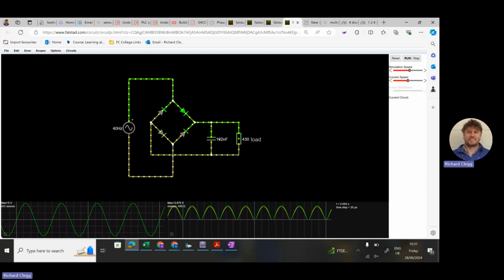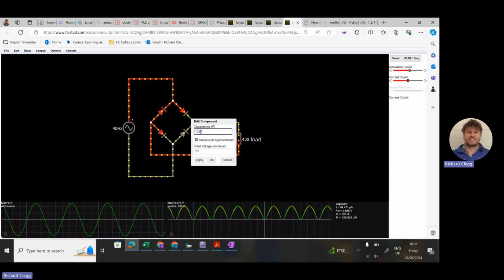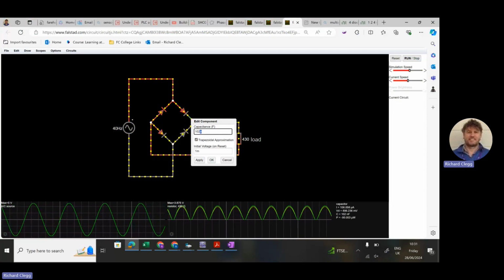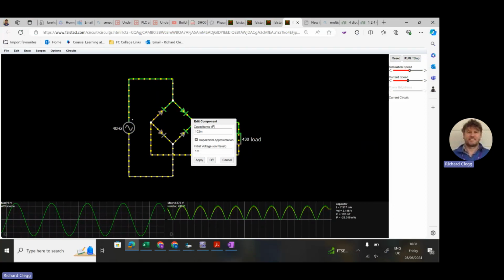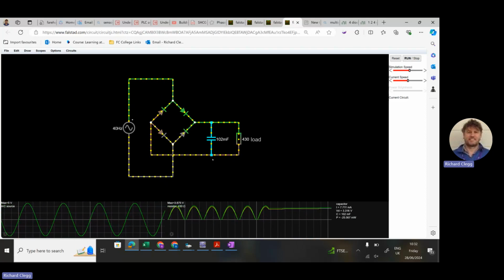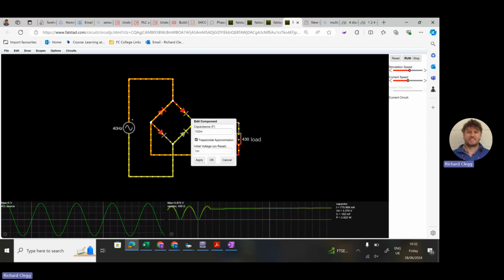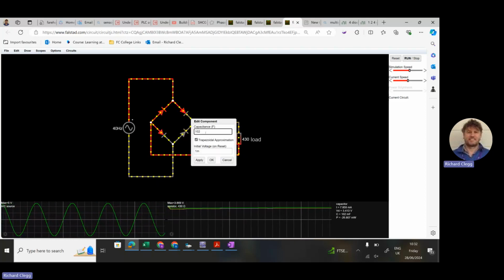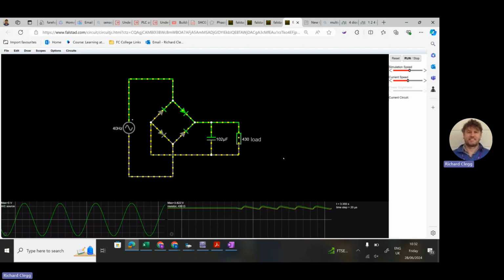So if you put a larger capacitor in there, it's going to smooth to a much nicer, smoother, slow changing, charging and discharging. So if I made this much bigger and we applied it, let's look at the waveform we get. And that's actually much, much smoother than the micro. We go back to the micro, we can put that in there and show the effect of that. Okay, so that circuit there is rectification.